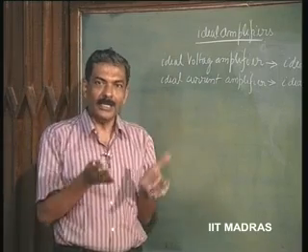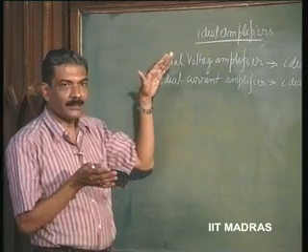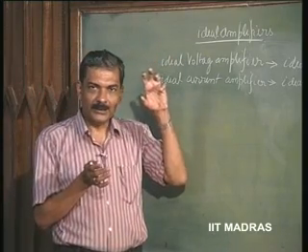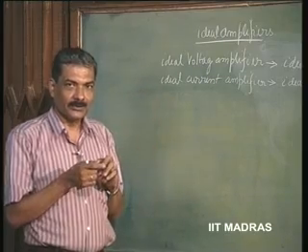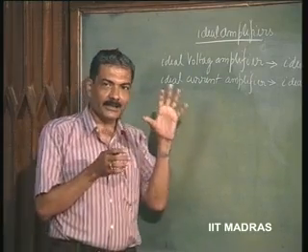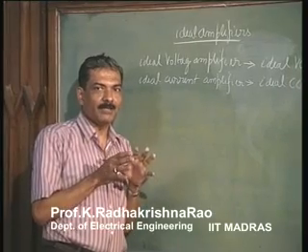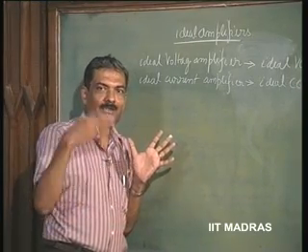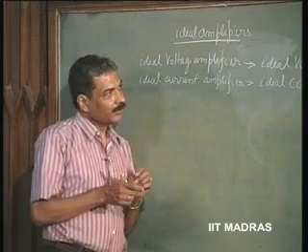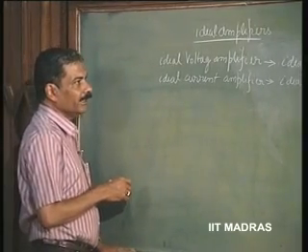But a non-ideal amplifier, on the other hand, can always be represented as a voltage controlled voltage source or current controlled current source. That kind of equivalent circuit can be put. But what it really is is determined by how it is driven by the source and how the load is connected. So, now the other two, obviously you must have thought of readily.